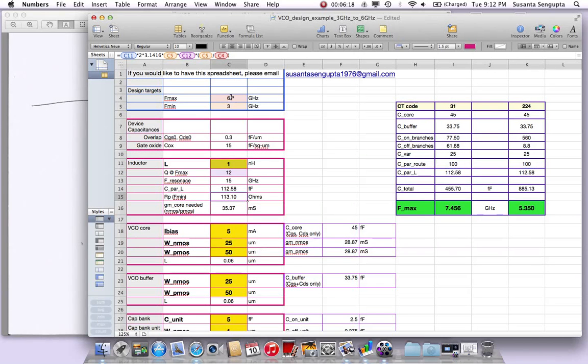C5 by C4 is the scaling down. So if the Q is 12 at 6 gigahertz, at 3 gigahertz I'm just doing a linear scaling for a simple approximation. Of course, it doesn't scale linearly, but here the Q will go from 12 down to 6. That's too pessimistic of an assumption, but still.